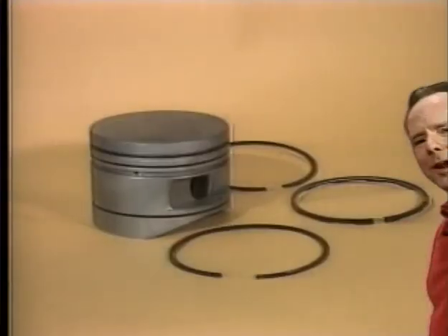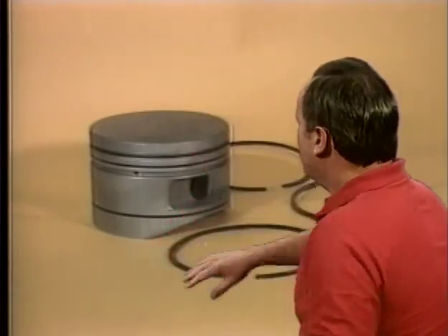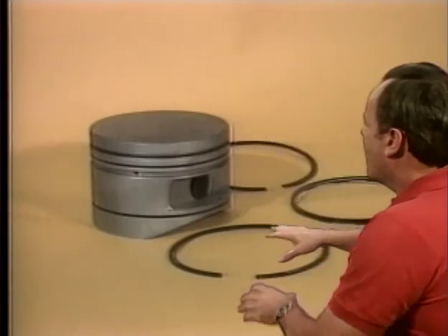Now let's assume you're putting an engine together and you want to make sure that you have a proper match of piston and particularly the rings to the cylinders of the engine. Well, it's a good thing that you're thinking about this because you can save yourself a tremendous amount of trouble by thinking in advance about it. Because you cannot use a hardened ring on a hardened cylinder. For instance, you would not want to use a chrome ring on a chrome cylinder, and the reason is you're going to wear that airplane out in nothing flat.